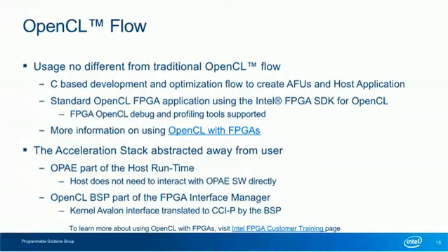To debug and optimize, all debug and profiling capabilities of the Intel FPGA SDK for OpenCL, which includes emulation kernels and load and store profiling capabilities, are still supported in the accelerator stack environment. For more information about how to use OpenCL to develop accelerators on the FPGA, please visit the Intel FPGA customer training webpage.